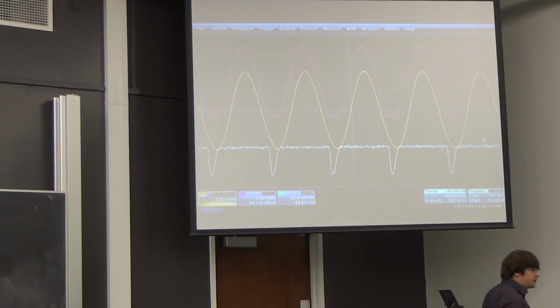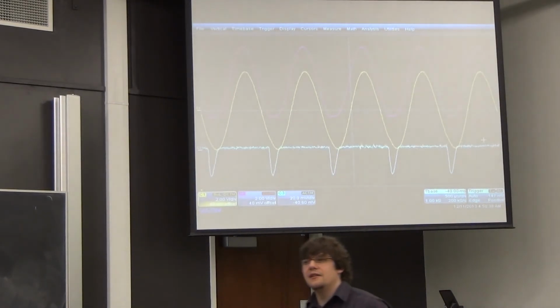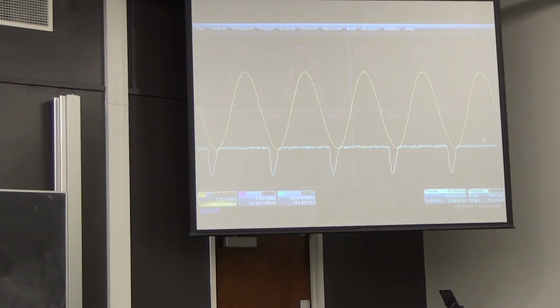Now, the way this circuit's actually rigged up over there, we are not looking at the charge change in the capacitor anymore, because that's a trickier thing to measure in an environment where mistakes are seen by everybody. So what I've done is I've measured the diode current instead. So we're not seeing a slope in this region here between the two peaks, because we're not looking at the charge going in and out of the capacitor anymore. We're now looking at the charge in the diode.